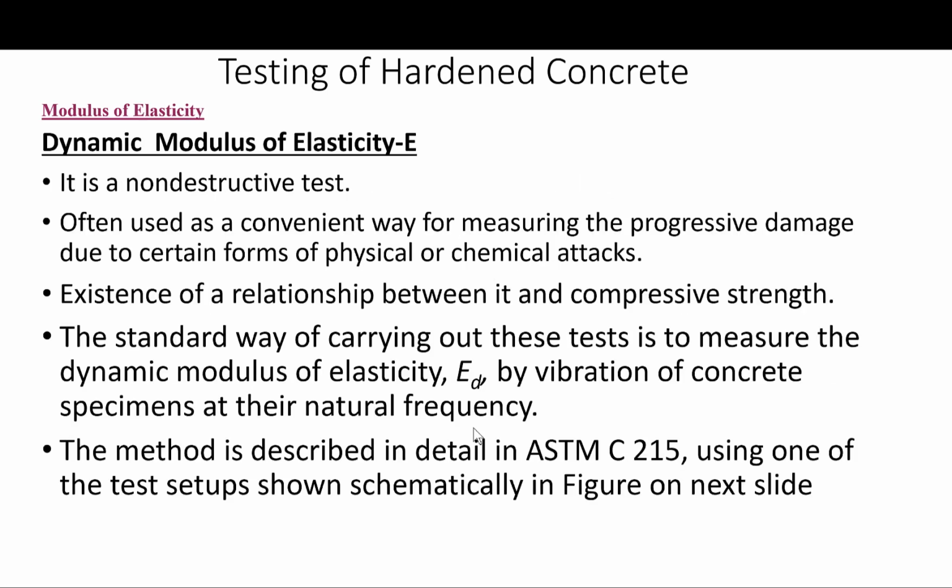Also, we can determine the dynamic modulus of elasticity. It is often desirable to have some non-destructive test for the stiffness of concrete specimens, to track the progressive changes in material due to sustained chemical attack, for example, or repeated freeze and thaw cycles, aging, or other factors that affect concrete.